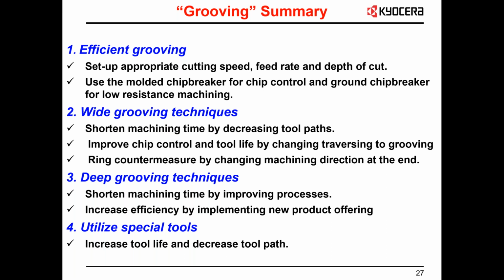Deep grooving technique, shorten machining time by improving the processes. Increase efficiency by implementing new product offerings, which for example is always find the better chip breaker, the better holder, jet coolant through, whatever we have to offer, that's going to increase your tool life and shorten your machining time. And also, when you can, special tools are always good.